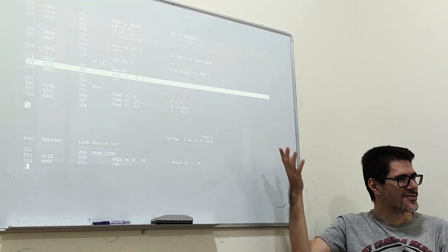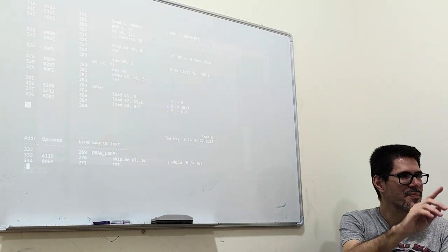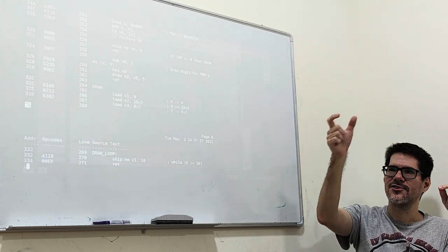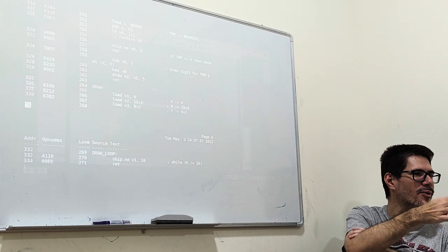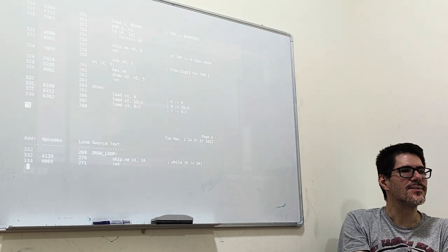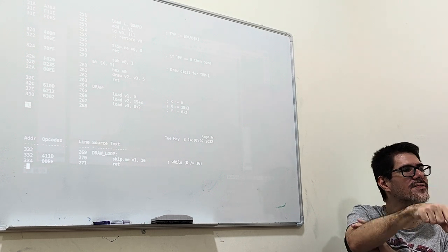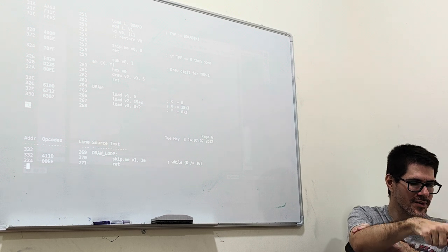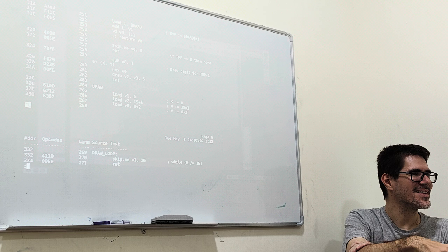So this is the kind of thing, and the same for the keyboard input. So you have an instruction that basically waits for a key to be pressed and then reads in the 4-bit value of that key into a register. Or you have another one which, given a specific 4-bit index, like a specific key, you can branch on whether it's pressed or not. So you have both key down, key up, and you have key press.